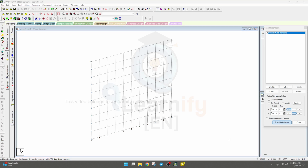Okay, so here you will see some important things, what we actually do when we start a project and go through to finishing. First of all, we need to set up, then geometry, that means modeling, then general, that means providing loads or anything, then analysis and design. Okay, these are the steps, and each menu or section has subsections.